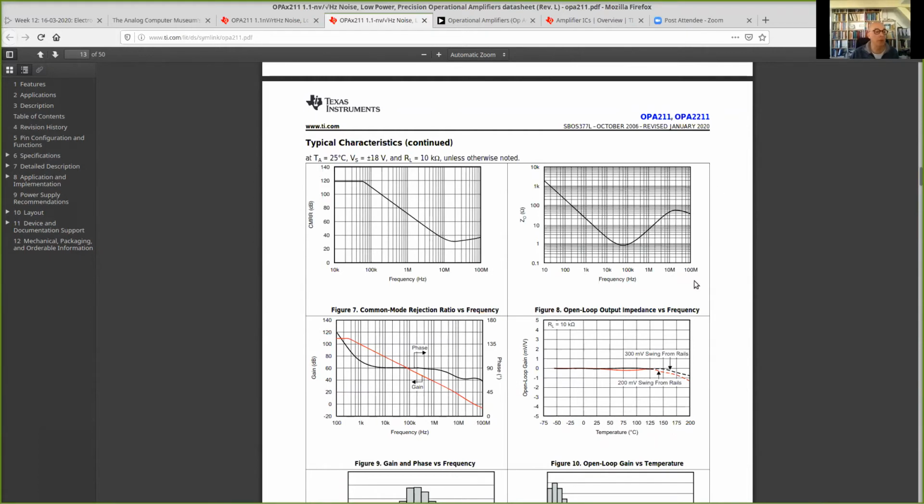So we have inductive, and we can see, let's say it is like 10 ohm at, well, 1.8 megahertz or so. And if you calculate it, I think it was a few hundred nanohenries. I don't want to do the calculation, but let's say just 700 nanohenry. I think it was, if I remember well, because I did it before.